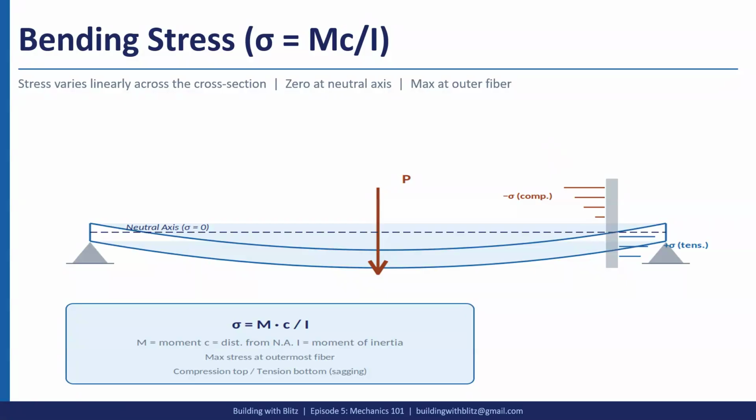So the M is the bending moment, the maximum, or wherever you're examining your cross section along the length of the member. So for a super technical term, it is the integration of moment, if we're looking at the entire beam, along the bounds of the length, with a length of 0 at one of the support boundary conditions, moving along the length. So you have an integration of the MC divided by I along the length. If you have a varying cross-section geometry, you'll take the integration rather than just using this formula.